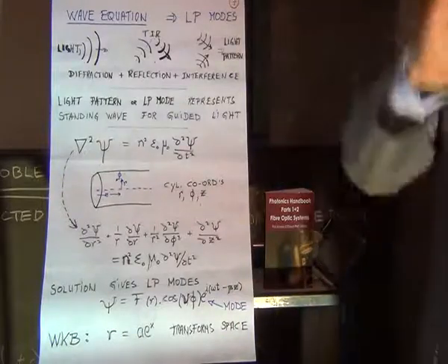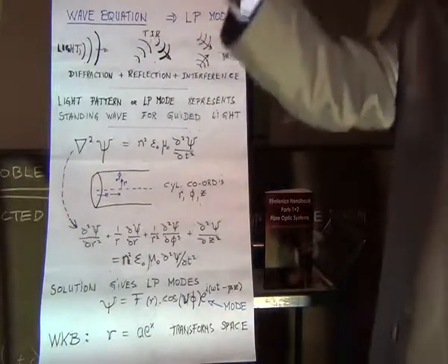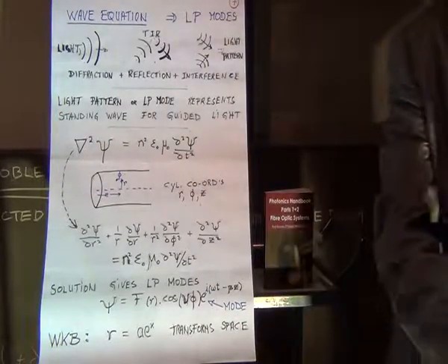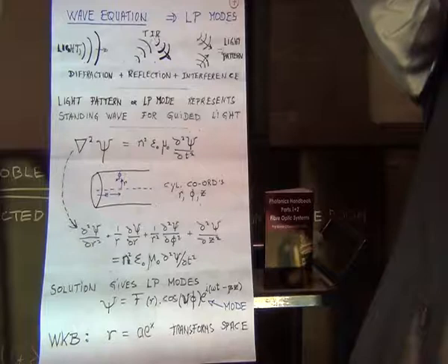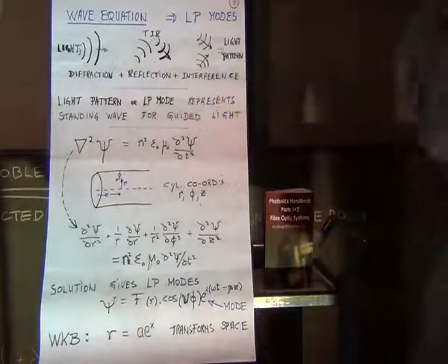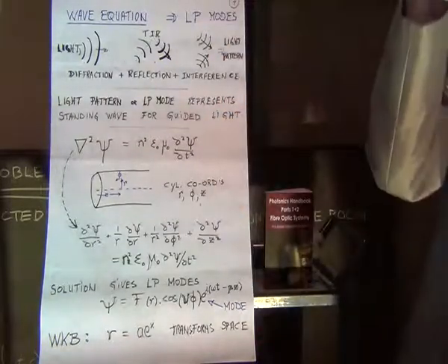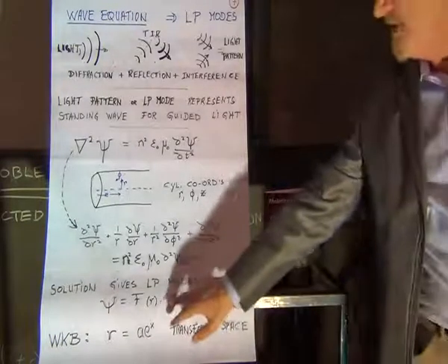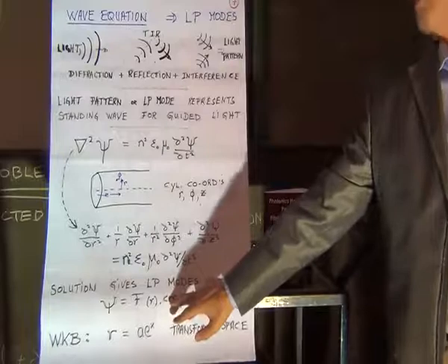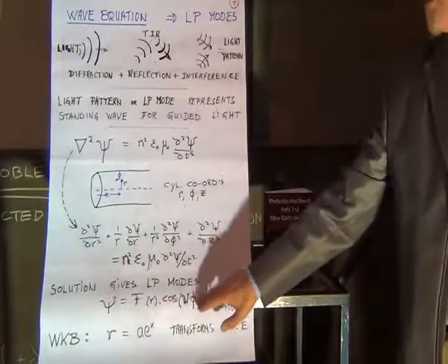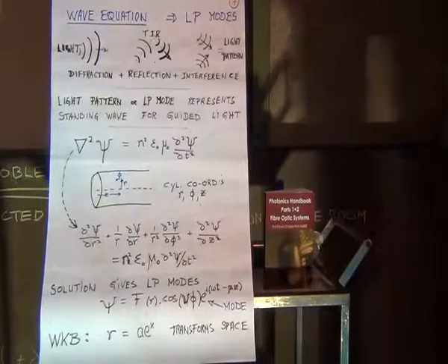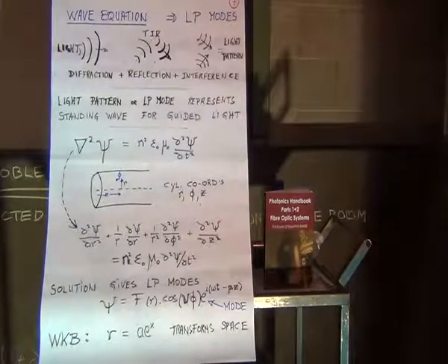In other words, if there is a bright ring corresponding to a standing wave or mode of the fibre, it's possible that the bright ring would be bright, dark, bright, dark, bright, as you go around 360 degrees. Okay? Well, that would correspond to some kind of a cosine periodicity. So cosine with respect to phi. And we put an integer in there to tell us how many times there are bright and dark spots as you go around the ring.